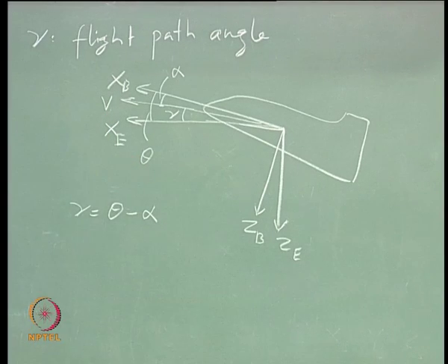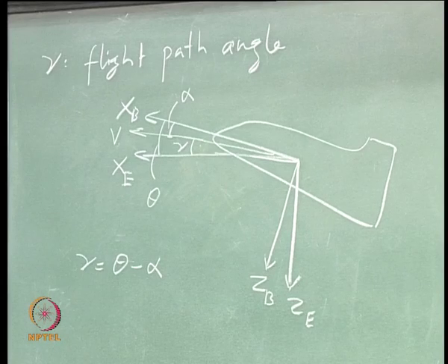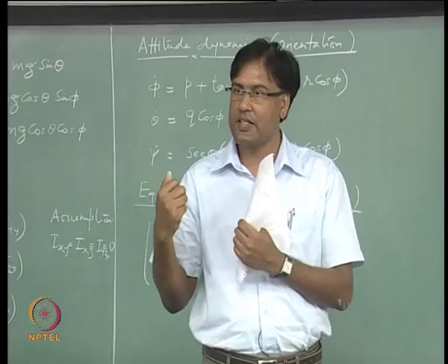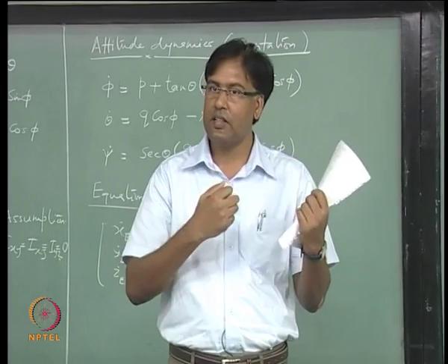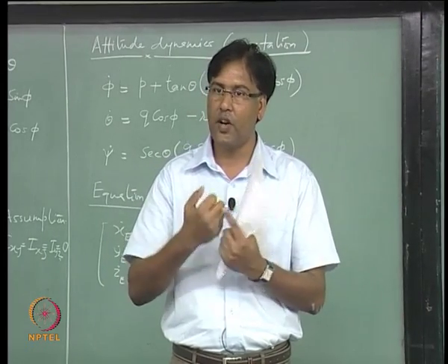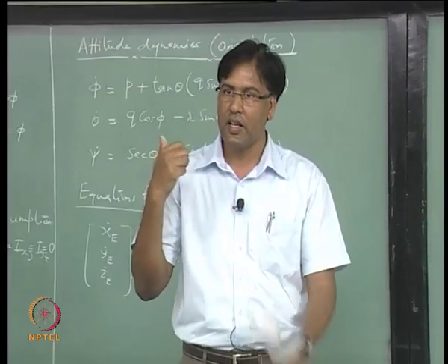Now, let us say my aircraft is having a velocity vector which is including angle of attack and side slip, right, it is not in 2D plane. Then you have to talk about 3 angles which will relate components of vectors in earth fixed axis system and the wind fixed axis system, right. We always have to talk about these 3 angles, right.